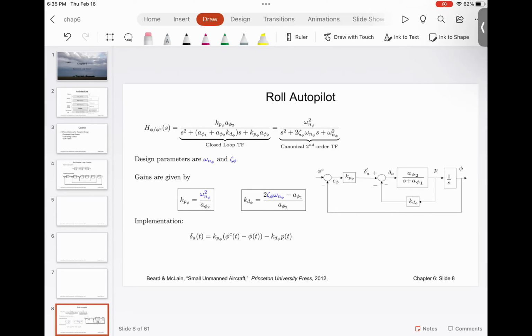In terms of springs, you can adjust the preload on the spring, or you can change the type of spring, or you can change the geometry of the spring, and then you can adjust the spring coefficient. So in practice it is possible to change the damping properties, and it is possible to change the spring properties. Many times the actuator is combined together.